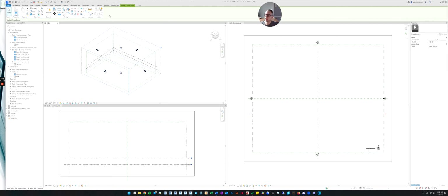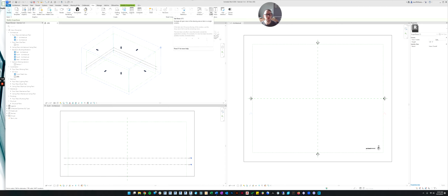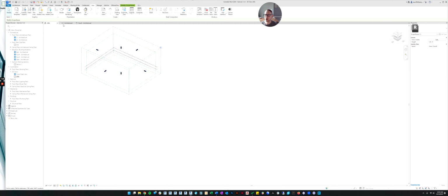Another thing I forgot to tell you already is if you go back to the View tab, in that same area with the Tile Views command, there's the Tab Views command. So if you want to put them back in tab format, you can do that, and it'll put them back all tabbed like they were before. So you can tile them or you can tab them.